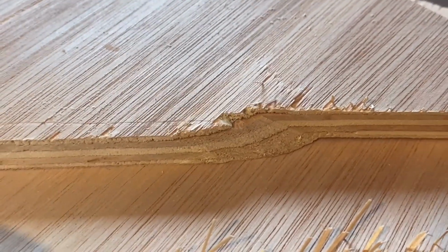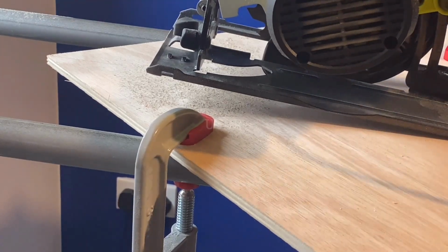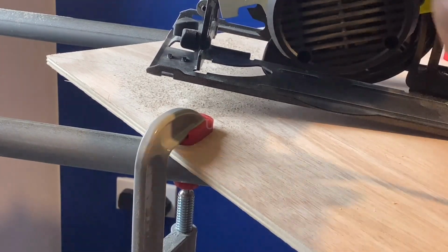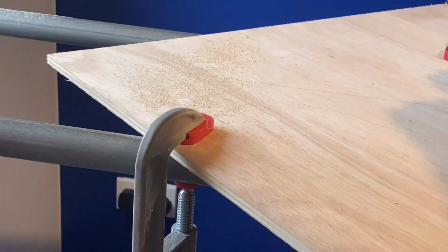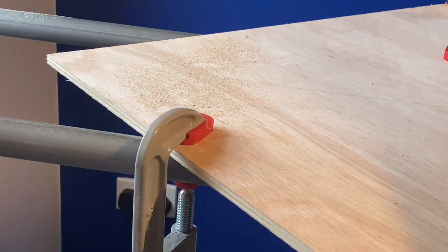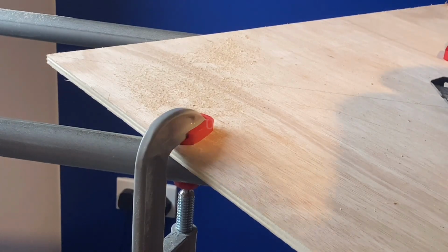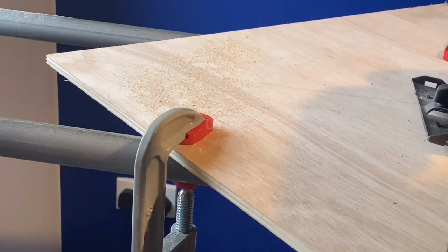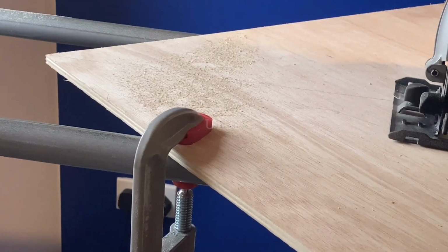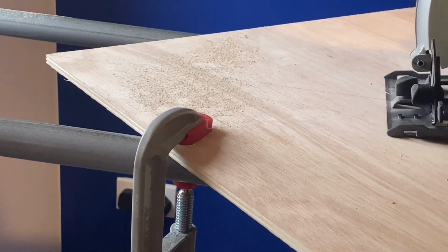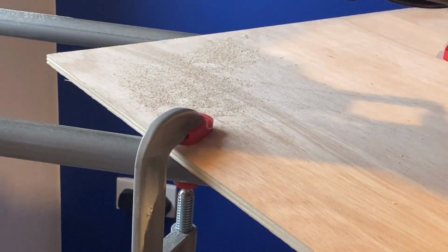The next step of the process would be to repeat and replicate the process, not that we know exactly what we're doing, to get finer quality cuts from the ripping blade. A workman is only as good as his tools, but we're just going to try and get good quality cuts from the ripping blade. But if we wanted optimal quality cuts, then your combination blade or your general purpose blade is the way to go, as they are capable of producing the finer quality cuts that you see on the side of the hardwood plywood.